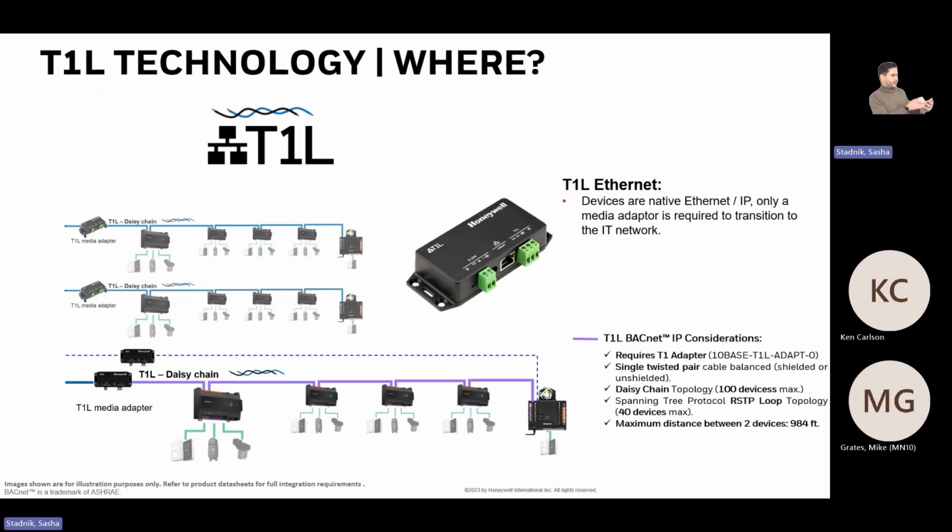Because when we were able to take that information from the chip, we use that information to latch a mechanical physical switch that is on the T1L controllers. That is normally closed, opens when it has communication, but immediately when the controller loses communication, it closes and bypasses it to the next port. That is what you guys know on the specs, like IP fail safe switch.